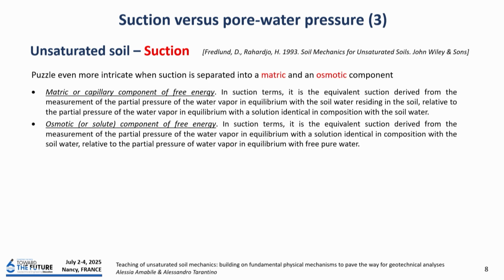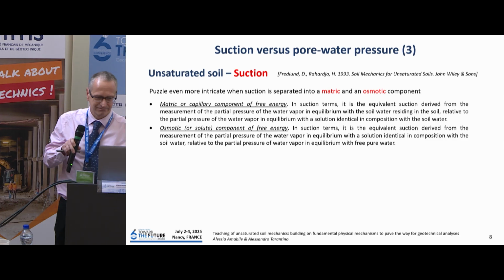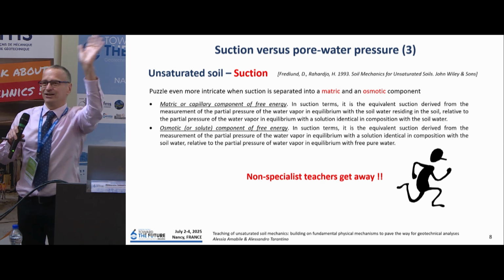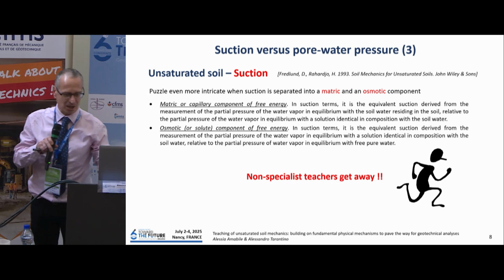But that's not finished. Second, you are hearing about matric and osmotic suction. Take a breath and come with me. Matric or capillary component of free energy. In suction terms, it is the equivalent suction derived from the measurement of the partial pressure of water vapor in equilibrium with the soil water residing in the soil relative to the partial pressure of water vapor in equilibrium with the solution identical in composition with the soil water. I'm saving you from the second. You are saying, no, this is not me. I'm never going for it.